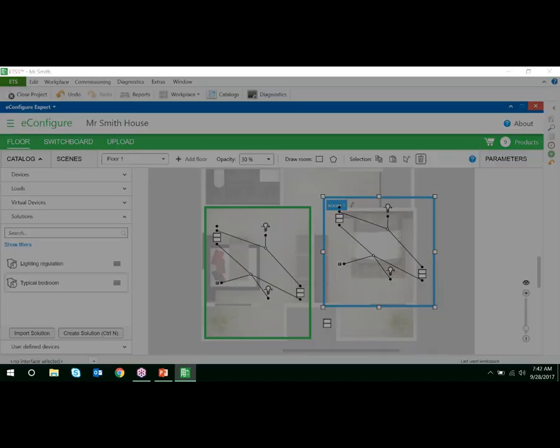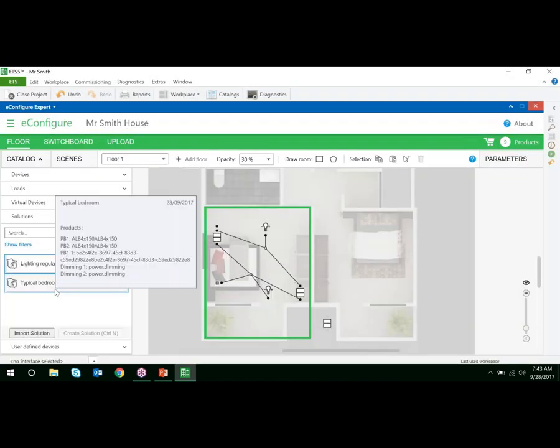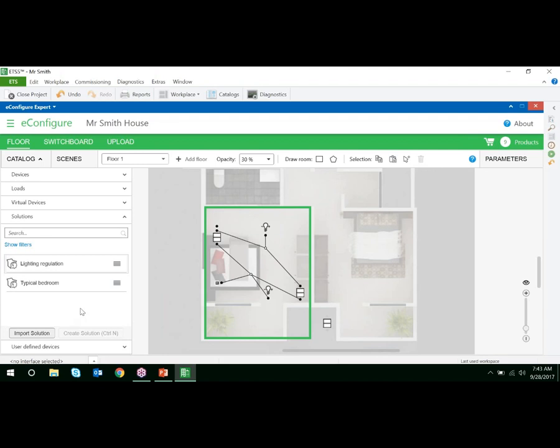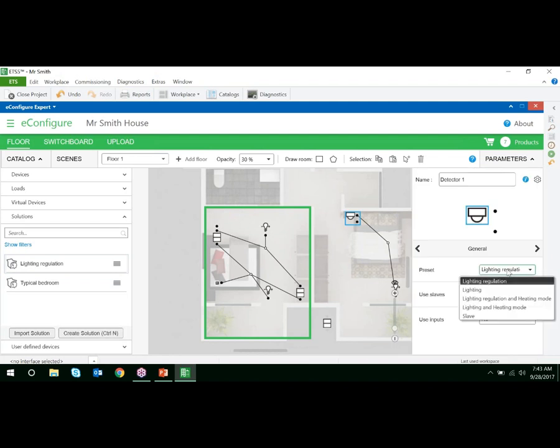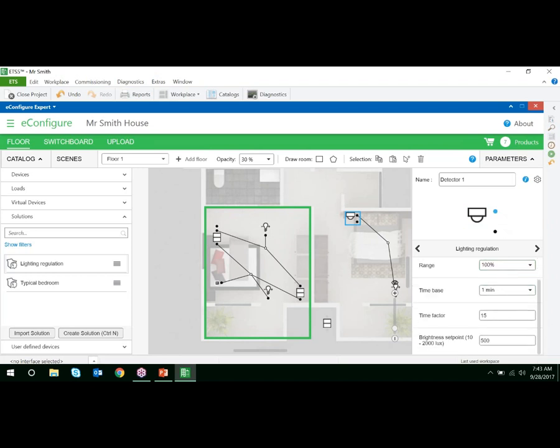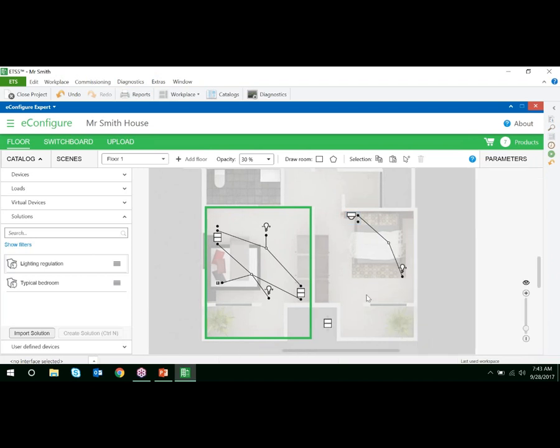It's very interesting because there is this example, but there is also the example of lighting regulation. You always have to check some parameters to make it clean. With this, automatically, you can do the lighting regulation and put it in all your projects. Here, we have also made it very quick. You define what you want, sensitivity, timing, lux, and you connect to the dimming, and you can save that and copy paste in all your offices. So it's also very interesting for this kind of features that need to be reproducible and easy to connect.